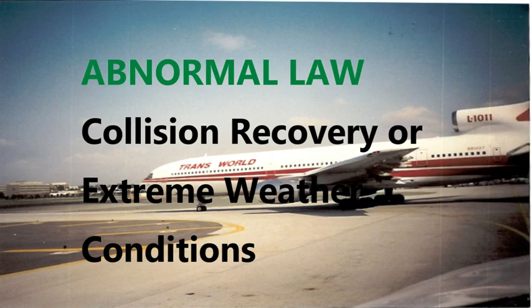Those are your 4 different flight control laws, and the computers that are there to read those inputs and determine what the command is going to the actuators of the control surfaces. And this is the whole objective with all of this. All these different computer systems are obviously to ensure that the plane is maintained in a safe condition at all phases of flight.